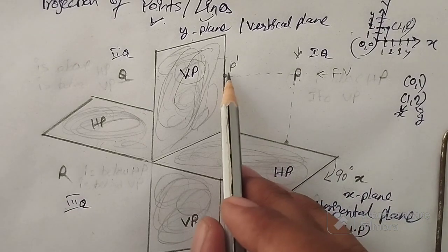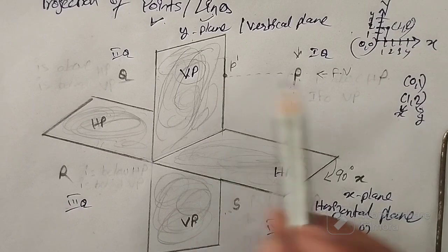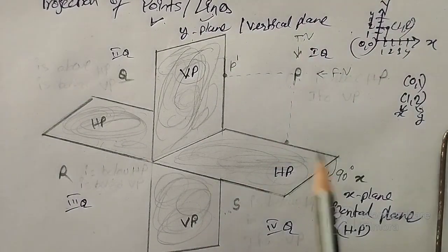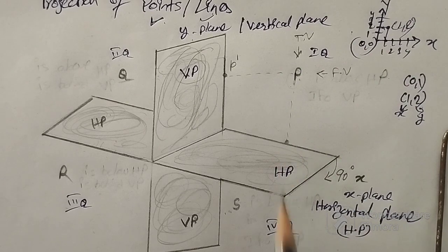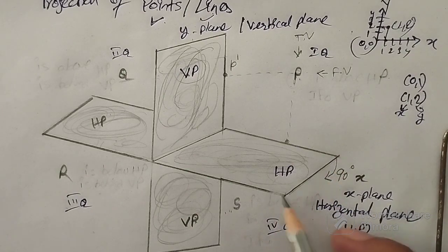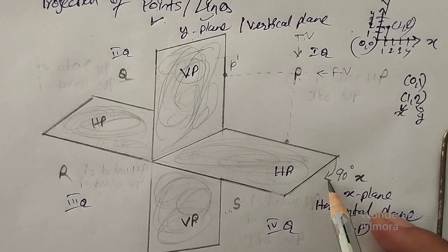Now there is a point P dash here, so in front view image is falling here, right? Now since I am looking from top view or the aerial view, image has to fall here, but I told it to convert into projections into 2D, rotate this HP, rotate horizontal plane to an angle of 90 degree.